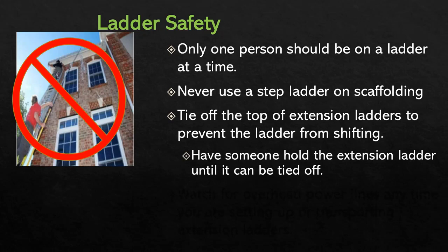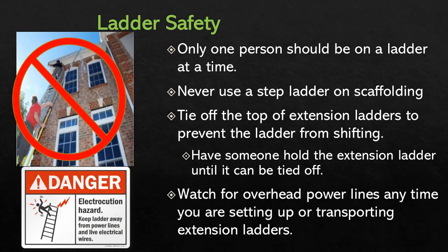As for how to protect yourself while the tying off is occurring, in this case you might have to recruit some help, have somebody hold the extension ladder down at the bottom for stability until it can be tied off. And please, if you're using extension ladders or step ladders or any kind of ladders made of conductive material, always watch out for overhead power lines.